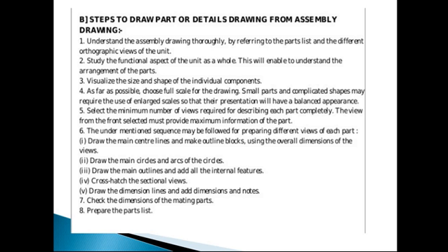So friends, this is a very important thing here. We require to locate every part, because we require to draw every part's details. Detail drawing means what? However many components are included in your assembly drawing, there may be 4, there may be 5, it may be 6. Once you locate each part, we require to separate it out, and every part we are going to draw separately. So this is a detail drawing.